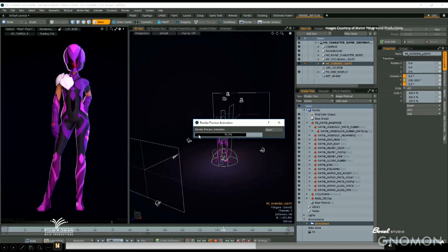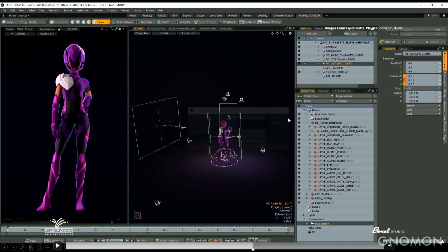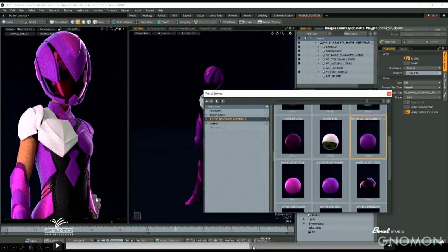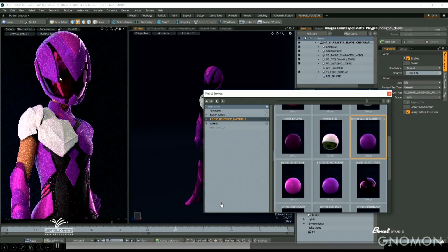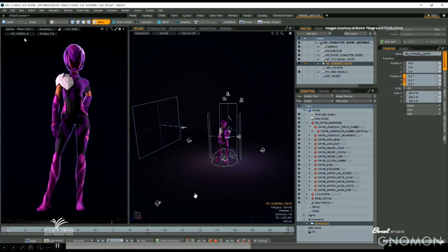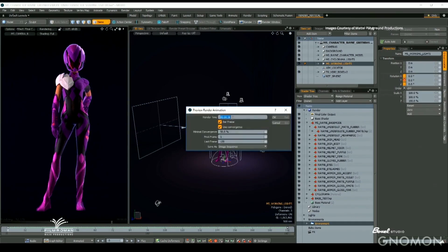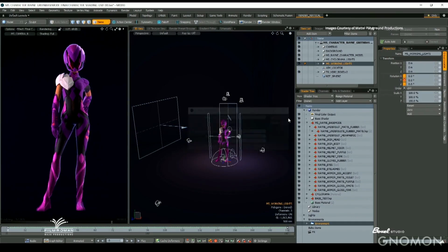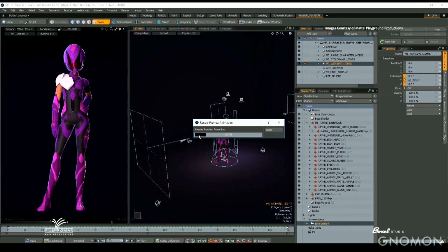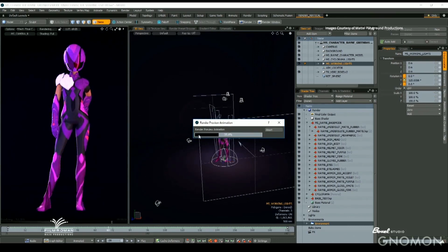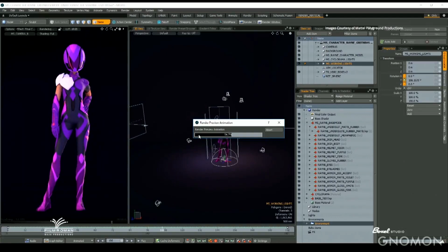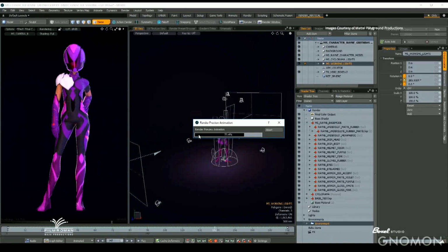I'm going to do it because I think it's important. I'll go back. The only part that was speed ramp was that part. Let me show you. There, once it's there, options, animation, 5 seconds, 192 frames, click OK. And that's the part that's speed ramp. The rest is 5 seconds per frame. You're talking about a 2K render.